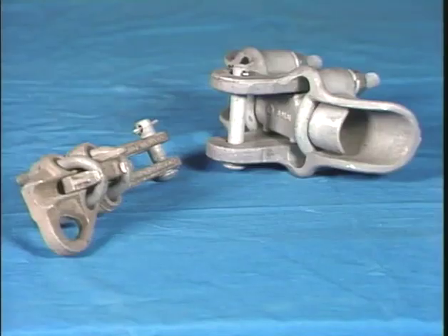It's important for you to ensure that inductance is maintained at design levels when you're working on a transmission line. If inductance varies from design specifications, impedance may increase, which may lead to an increase in power loss. One thing you can do to maintain inductance at design specifications is to use proper clamps on transmission lines. Clamps are the devices that connect two conductors together. You have to use clamps that are the right size to maintain the proper cross-sectional area of the conductor. As we've seen, the size or cross-sectional area of a conductor is one of the factors that determine inductance.